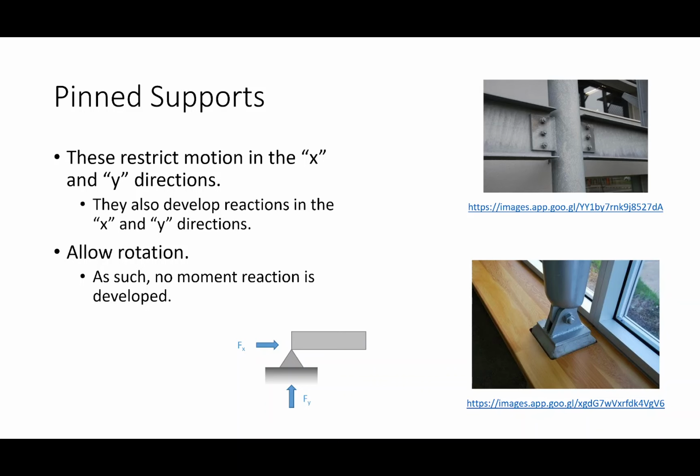The first is called a pin boundary condition, okay? So when I draw that out, maybe on the board or here on the screen, I'll typically use a triangle, okay? And I kind of use a triangle because they usually actually kind of look like one. And a pinned boundary condition will resist motion but not resist rotation. Like it'll resist translation but not rotation, okay?